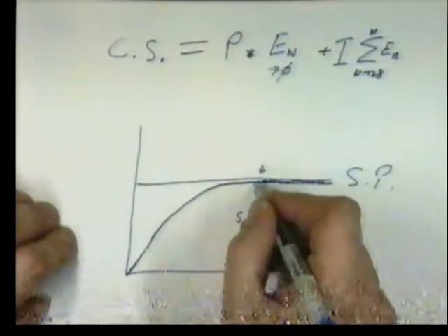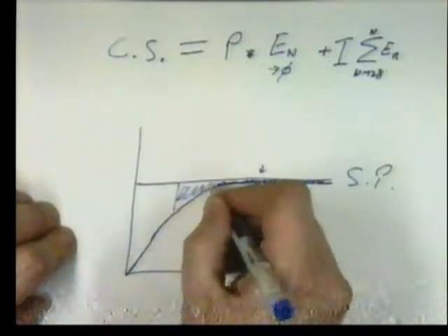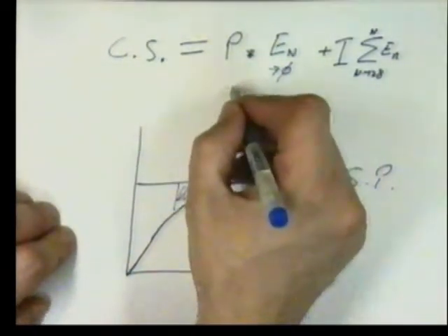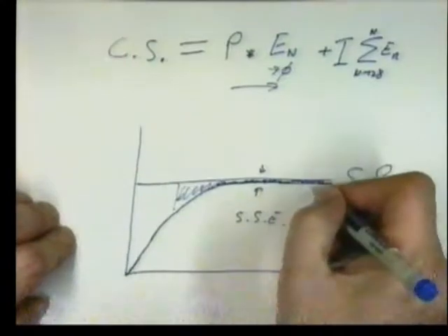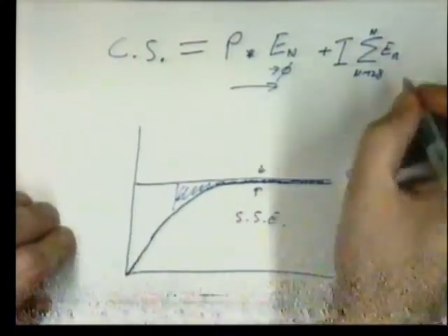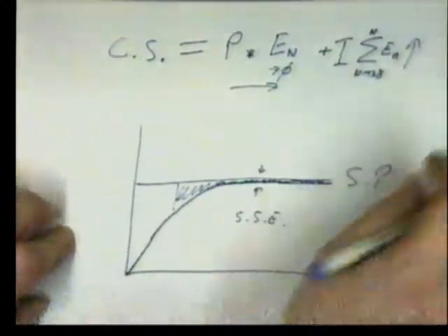What we do is if we integrate the error over history, then even though this term has tended to 0, if we remain in the steady state error position, this term is growing. So when there are very large errors, the proportional term will dominate the system.